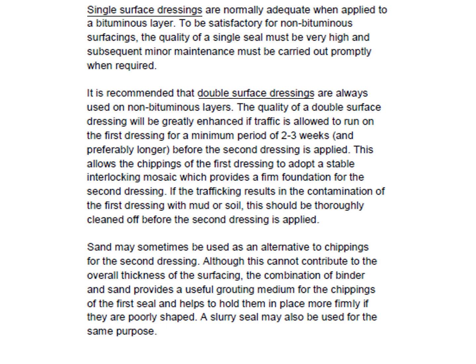Well, keep this in mind that in the surface dressing, what we do is first we spray bitumen on the surface and then small size aggregate is placed upon that sprayed bitumen. So in this way we will have the surface dressing. Obviously in the double surface dressing you will have to carry out this exercise 2 times. So ultimately you will have the double surface dressing.